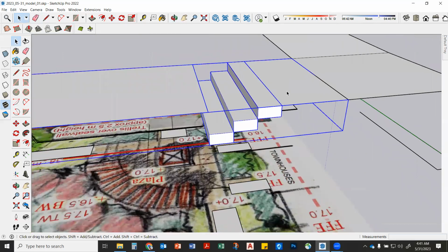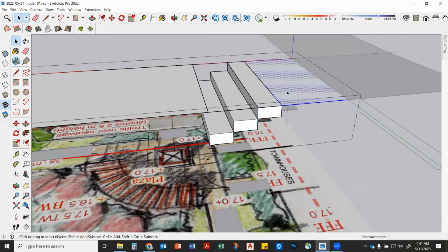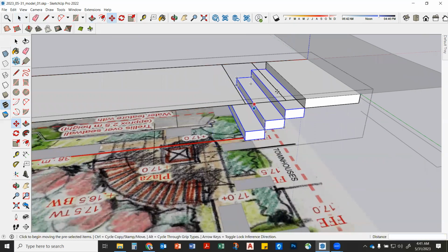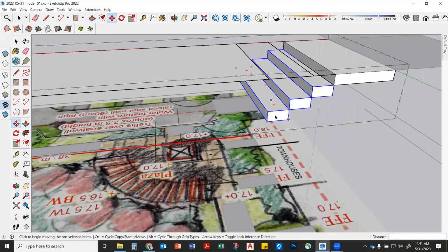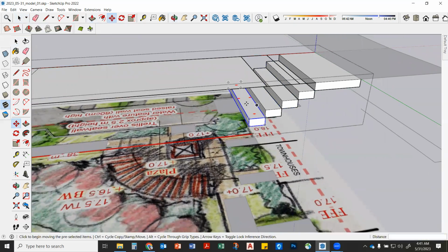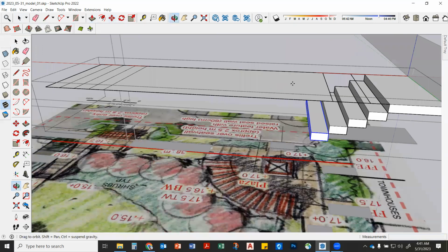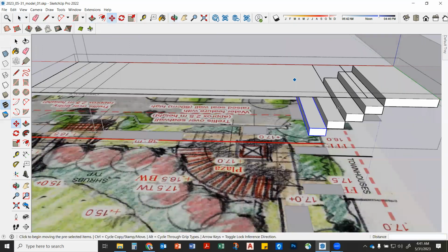So we'll go ahead and move. Let's move this down. We'll double click in here. Push this down 0.15, right? And then I'll snag those stairs I just put here. Move down to there, right? So now we got 1, 2, 3, 4. Still need another one. M for move, select there, copy to there, right? So the landing is going to get a little bit shorter, right?